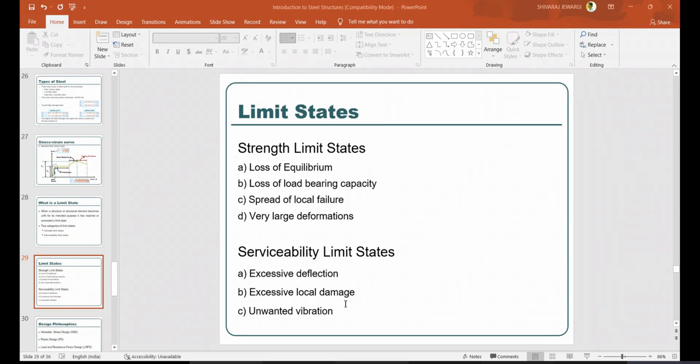Rolled steel flat. The difference between plate and flat is that in plate there is a considerable thickness, whereas in flat the thickness is usually neglected. They are worried only about the length and width dimensions. Rolled steel strips, strips of width like 6 mm, 10 mm, right? So length and width are the major parameters, and thickness is negligible in strips also. So these are the 8 to 9 different shapes of steel structures which are available in the market.